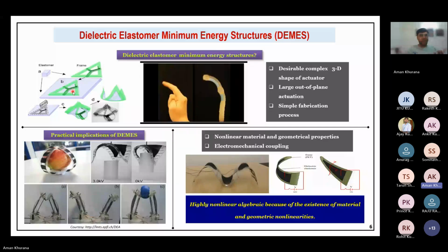So this dielectric membrane is pre-stretched. What does that mean? It means that it will have some strain energy stored in it. Because of the stored strain energy, when you put it over the frame, over the surface, and you cut it, remove it with the external mechanical constraint. It is not just put over, we have a mechanical constraint, like some spring type of structure also. I will show you that also. And when you remove it with the help of a razor blade, the entire configuration will try to attain a configuration that is characterized by the minimum energy state. In this universe, everybody wants to be stable by minimizing their energy. So this structure is also similar to that. It is the initial configuration in which no potential difference is applied.